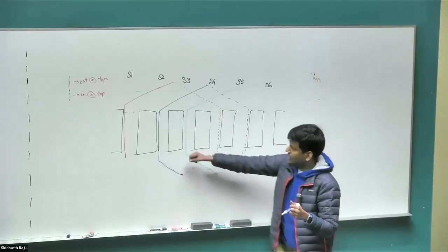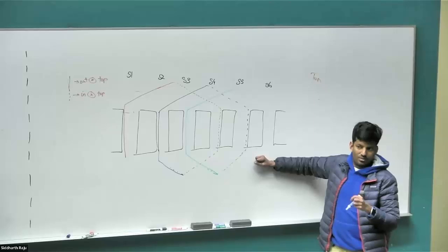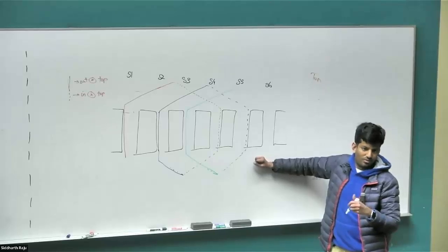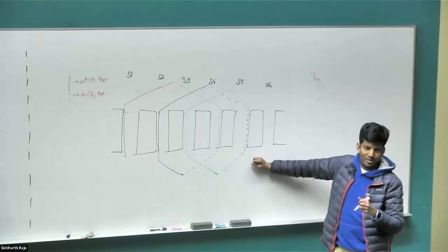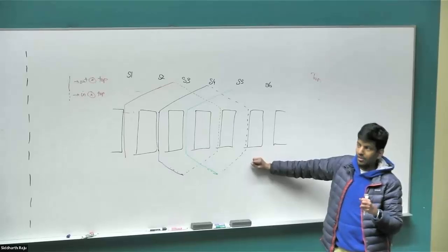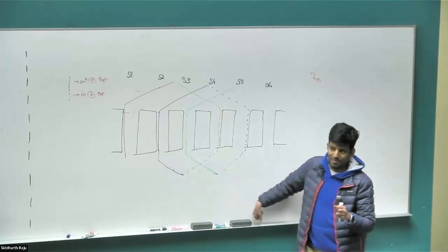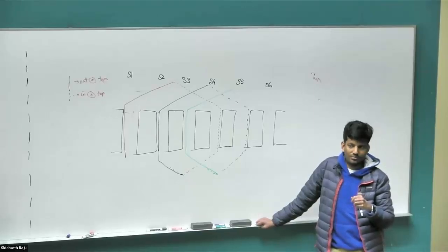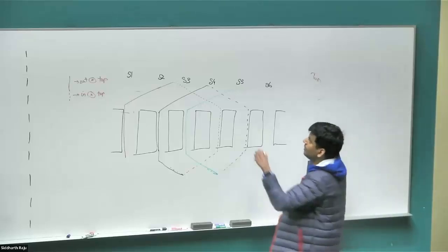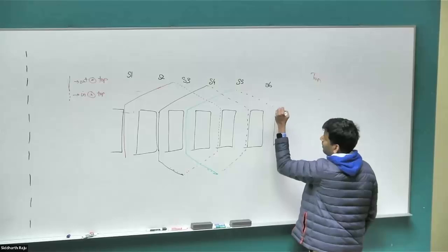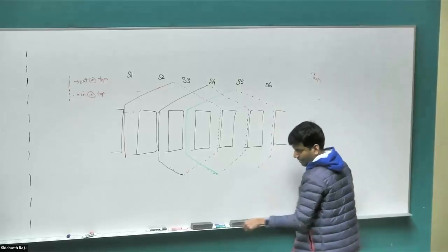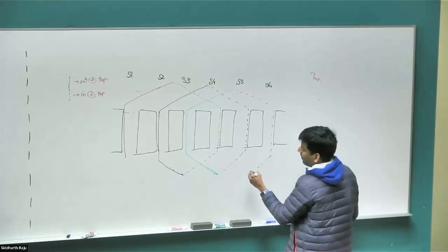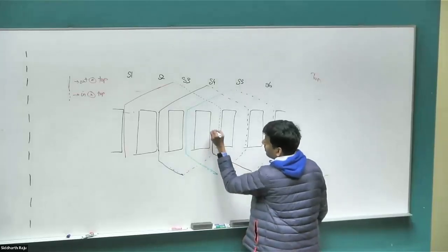Okay. So from slot 3, where is it going to go on the top? It should be in your memory by now. On the top, 180 degrees apart. On the bottom, 2 slots behind, in case of a 6-slot machine. On the top, where is it going to go? Anybody who hasn't answered so far? Want to take a guess? 6. Thank you. So on the top, it goes into slot 6. On the bottom, it goes into slot 4.